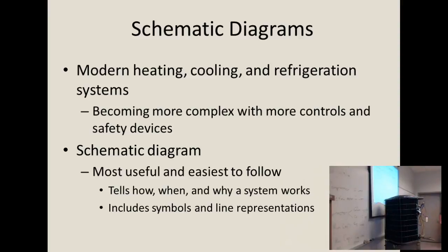Now, on that fan, the wires are not always going to be black, yellow, and brown. We can either look at the motor and read what it says, or we're going to use our meter today to learn how to figure out which one is run, start, and common. A lot of you already know how, but we'll go over it again.